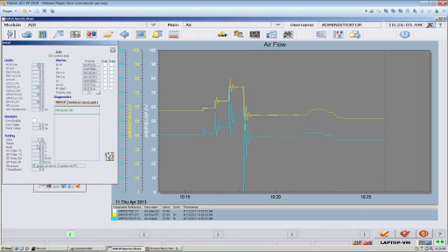and my reset time is my manual mode time constant. I measured that at 5. Remember, the 20 seconds divided by 4 was 5. We enter that and we're done. No calculation really even. So now let's double check my, see again, I didn't quite click on that value. 0.26 is my gain. That's what I want. A reset of 5. It's a pretty good example there of, always check your entries before you hit the mouse or hit the return button.